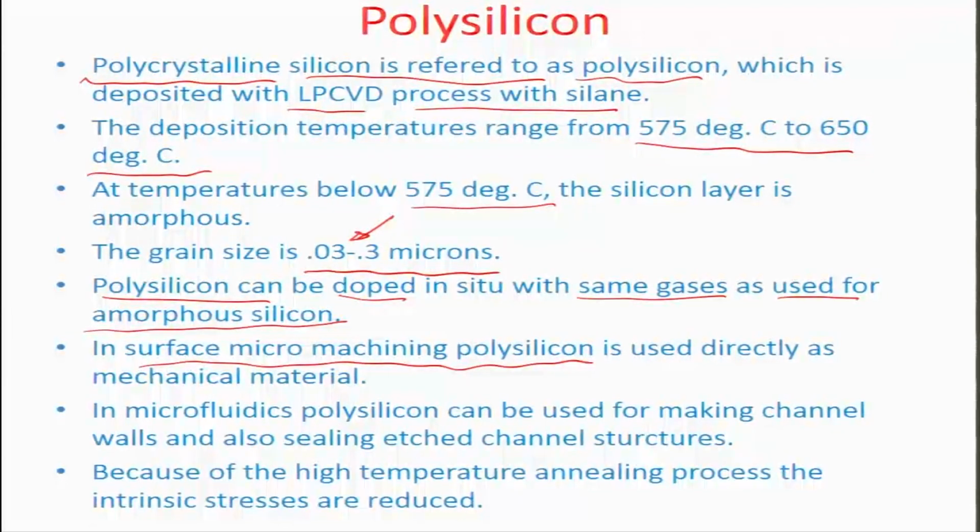You saw how a layer was deposited on a sacrificial material, and the sacrificial material removed to create some kind of a small containment, or confinement, with the layer on the top. So, it can only be possible if the layer on the top is mechanically robust enough, which can sustain the pressures created because of removing the sacrificial layer from underneath.